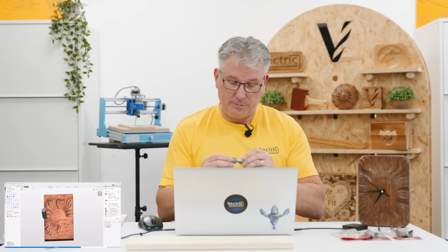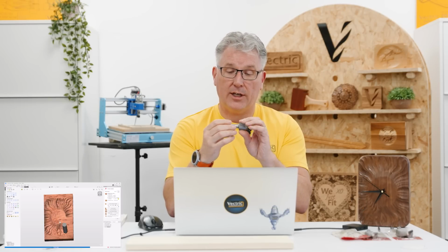Again, it's going to take a few minutes because I've got it set up to a high resolution. This is quite a big cutter because I really wanted to see what was going on when we did this. And again, you can fiddle around with different size V-bits, different size ball nose end mills. Now in our particular case, I'm really quite fortunate because this ball nose that we're going to use has a really large shank. It's a 1/2 inch shank. So we happen to have a 1/2 inch collet for our machine.